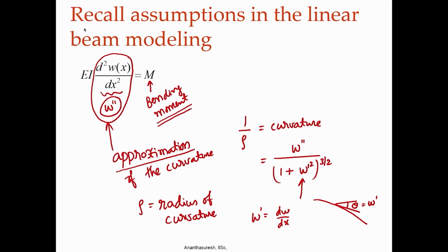The other is more subtle, which is the bending moment. We write the bending moment in the original configuration. If I have a beam like this, since we are discussing a cantilever beam, let us consider that I apply a force anywhere, but in our case we are going to apply the load at the free end, a transverse load. We write the bending moment diagram in this configuration rather than in the deformed configuration. In the case of nonlinear analysis, there will be a transverse displacement, we can call it WL, as well as UL, which is in the axial direction.